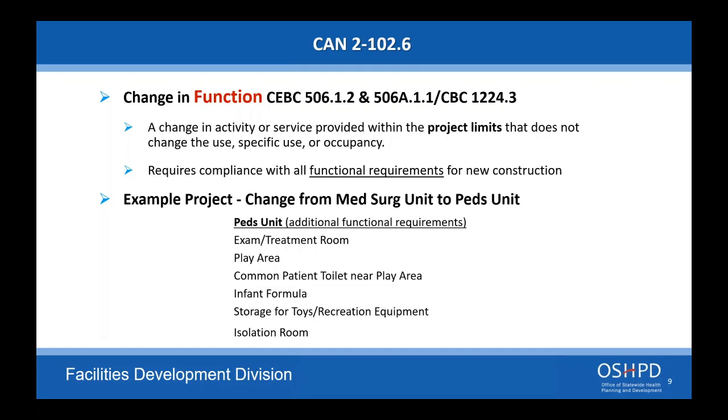Everything in that room now is considered new for an alteration. So that room needs to be compliant. Especially if you're changing walls, you're going beyond. Before we were talking about equipment replacement, not triggering accessibility. This would trigger accessibility. This would trigger compliance with the fire alarm system.